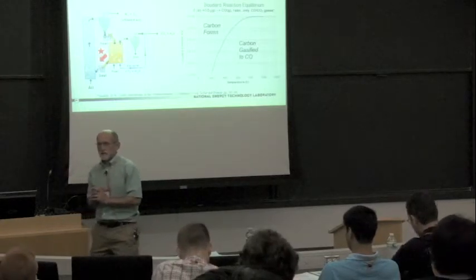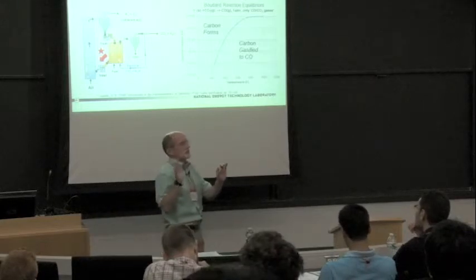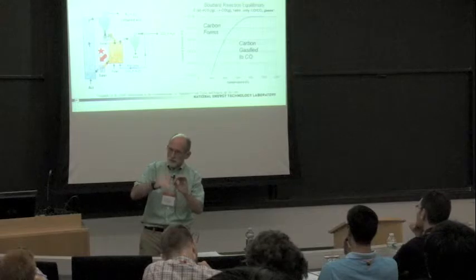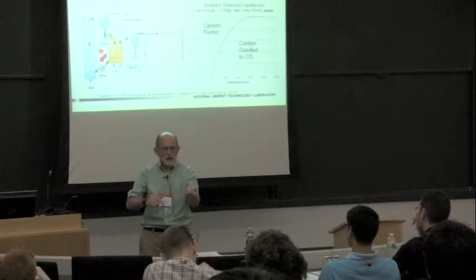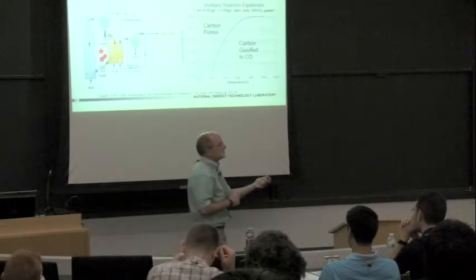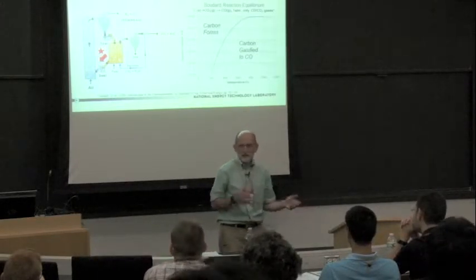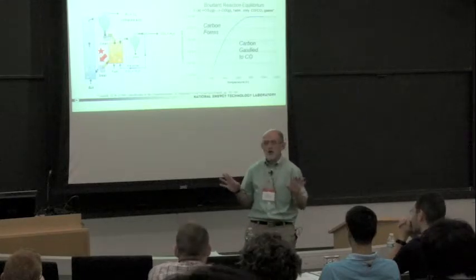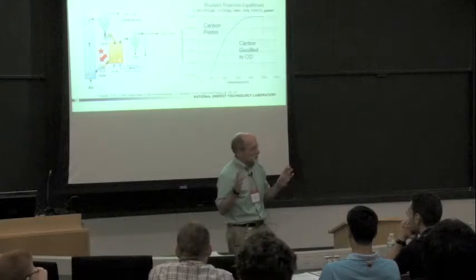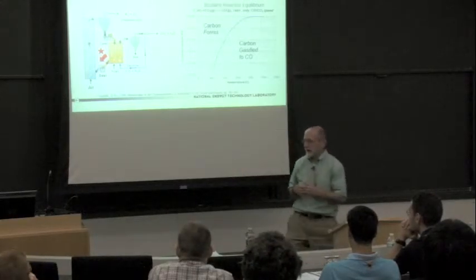All right? Because you could imagine if you had iron oxide that you reduced down to one of the reduced states, and there's carbonaceous fuel near it, you could very easily make coke, carbon, right? You don't have to worry about that, as you're going to see in a minute, as long as you don't leave the oxygen carrier in there too long. But nothing's perfect, so you may actually have to worry about carbon being carried back out of the system.